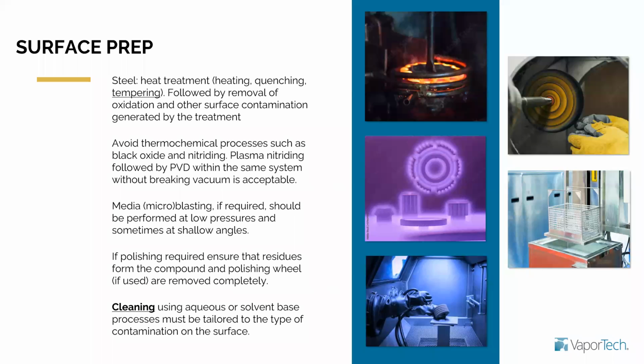So you will find some of those hairs or particles from the polishing wheel inside, and that will be detrimental to the process of applying the PVD itself. But also make sure that whatever you use as the abrasive or the paste to do the polishing is easily removed, right? You can't just polish a part and take it to the PVD or PECVD chamber.